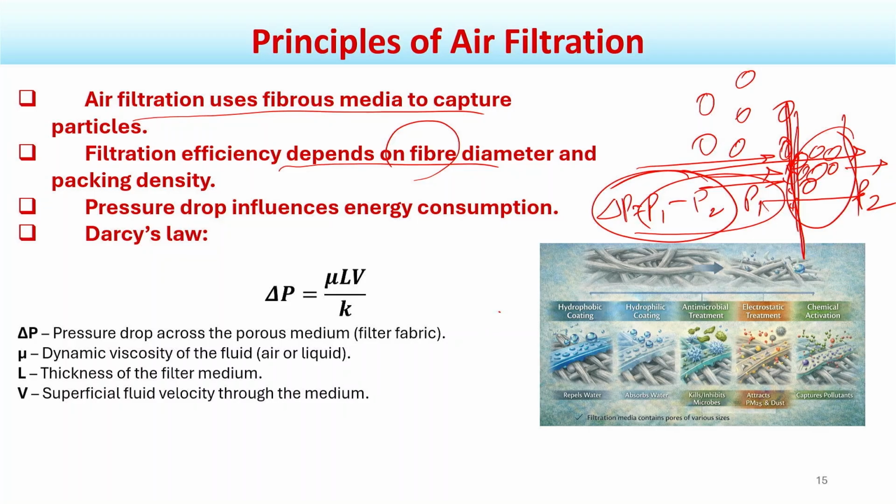That is why nanofiber coatings or very fine fiber structures with micropores are used only where the air velocity is very small, and where air velocity is very high, we should use an open structure.